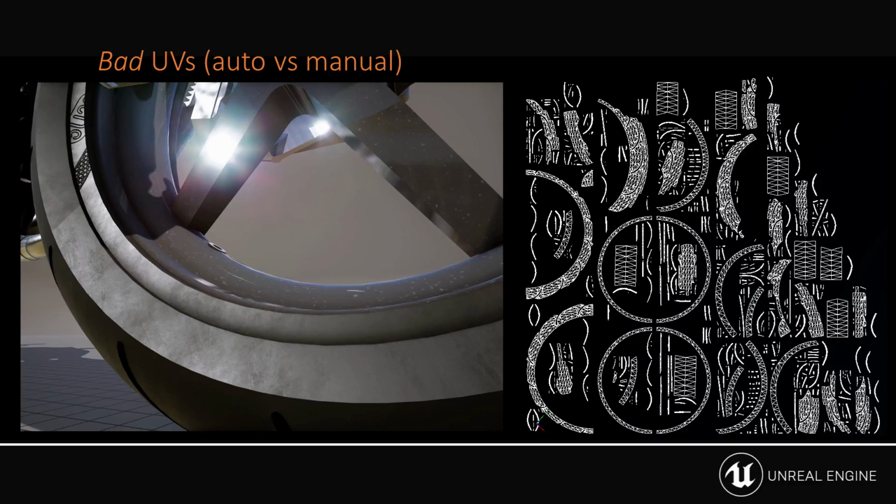Here we have a simple tire in the scene. And we can see up here on this corner that we don't have very good texture details. Something's going on in there. And there's also a seam, which is probably from the light map baking because of the bad UVs laid out in here. Now this tire is laid out using automatic UVs. As we can see on the right with these UVs laid out here, you can see the faces of them are scattered quite randomly. And this isn't going to result in a good texture placement.